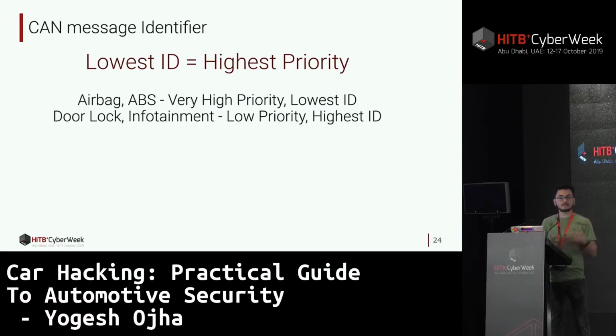If there are two packets coming at the same time, it needs to have arbitration. Suppose there are two nodes sending messages at the very same time, the message with the dominant ID, the one with the lowest ID value, will override the other.